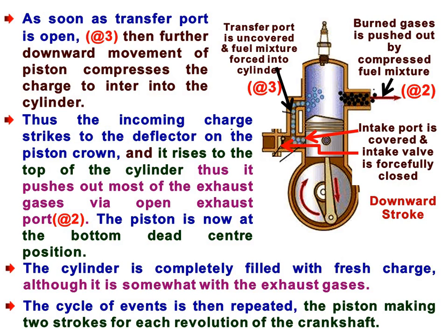But as there is a mixing of intake and exhaust in this system, some exhaust gases may not expel out from the cylinder. So there may be fresh charge inside the cylinder as well as some exhaust gases.